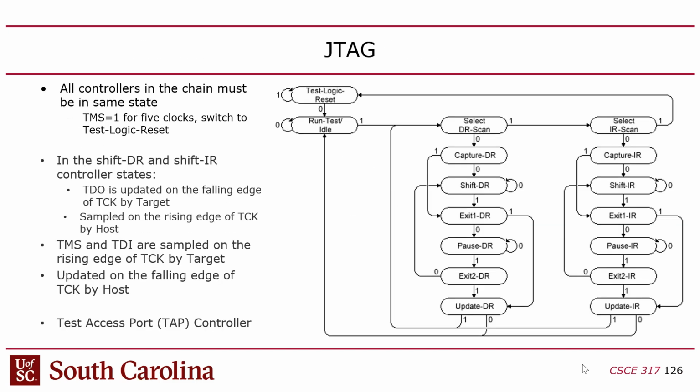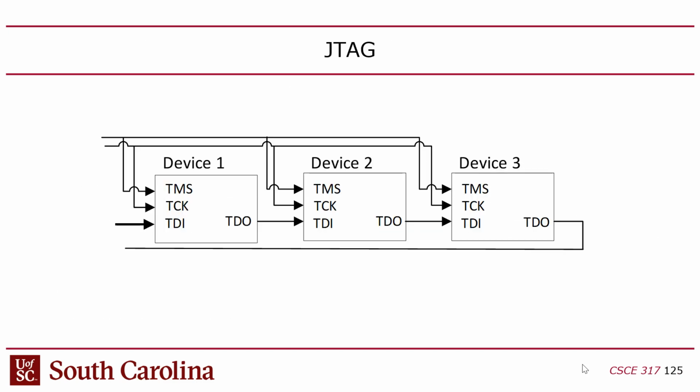Okay, and then JTAG. JTAG is also a serial protocol. It's kind of like SPI in that it's a big shift register. The important difference with JTAG is this TMS input, test mode select. Test mode select is a control bit that allows you to put every device on the JTAG chain, the chain being linking these guys up, TDO to TDI to TDO to TDI,